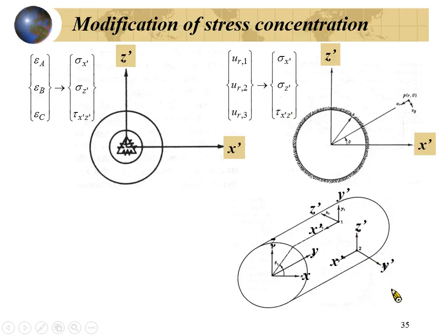So here shows you a tunnel where you're trying to make the surface relief. You have a tunnel, you could measure the stress in this point and in this point. Like a flat jack. You still remember you have a PV and pH. So you will have two variables or two unknowns. So right now you need two equations. So I try to determine the sigma theta here and the sigma theta there. So I will have two equations. So I can solve the PV and pH.